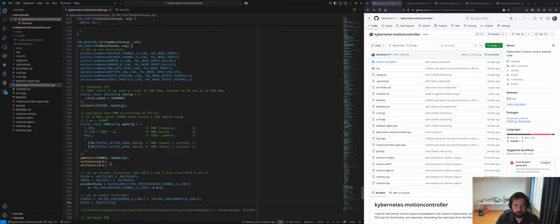Well, actually, I don't know if saying by default is correct, but at least in the configuration we had pulled out of the sample, it was configured to use timer 1 as the clock source for switching tasks, whereas I needed to use timer 1 for controlling the servos.